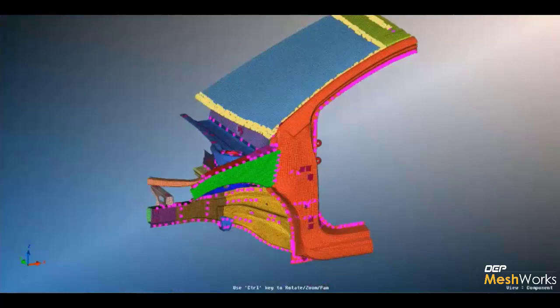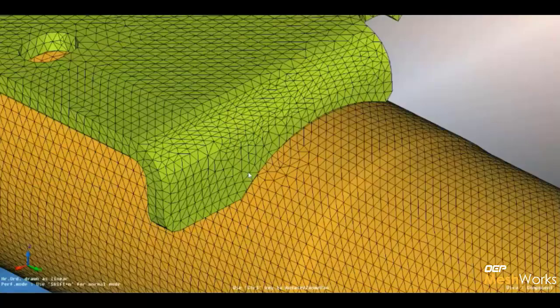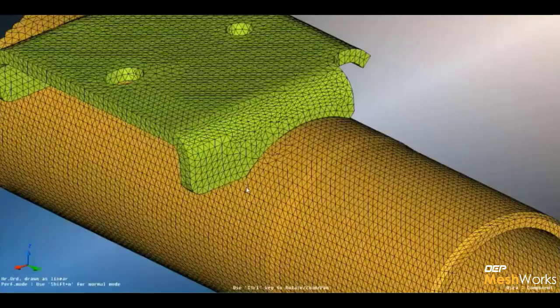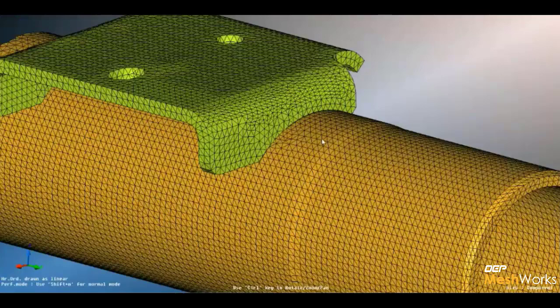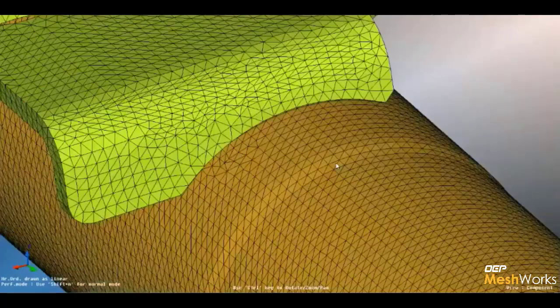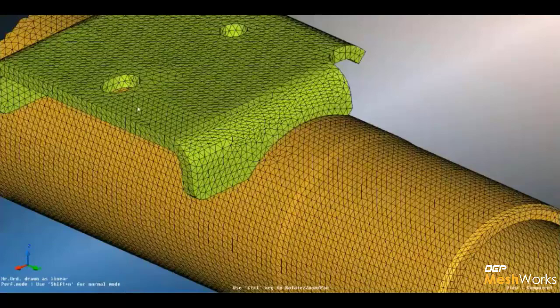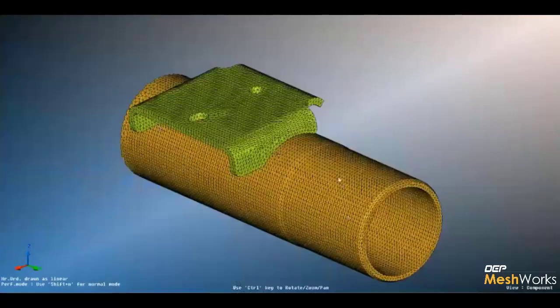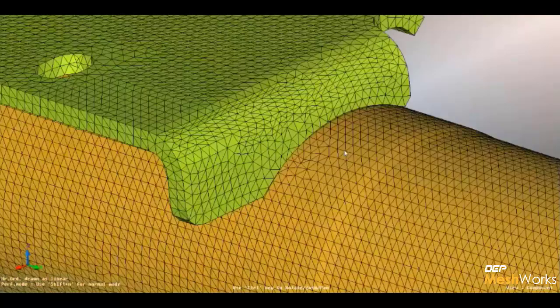So this is one example of a vehicle conversion model. The next example I would like to take is a tetra model, wherein we would like to create weldments for tetra elements. The usual process to create a weldment is to create CAD data, or if existing weld data is available, the user can use it, trim the lines, and then do all the regular meshing process to bring up the node-to-node connectivity. But in the case of this particular tool, none of that is required. There are no dependencies. The user can mesh the bracket component separately and the axle component separately, and then come to the automation tool.